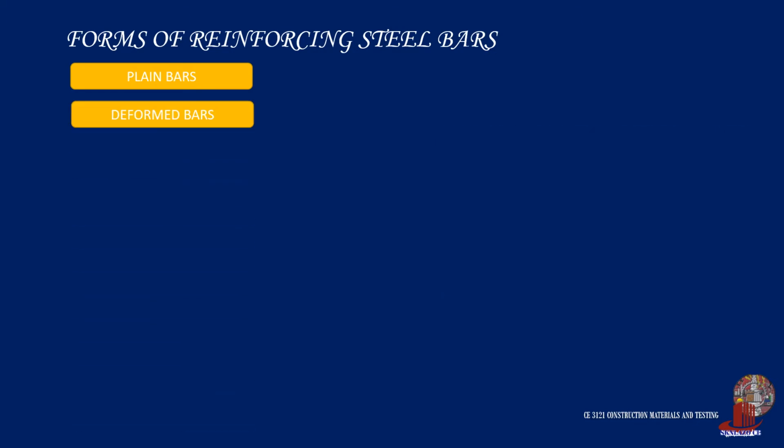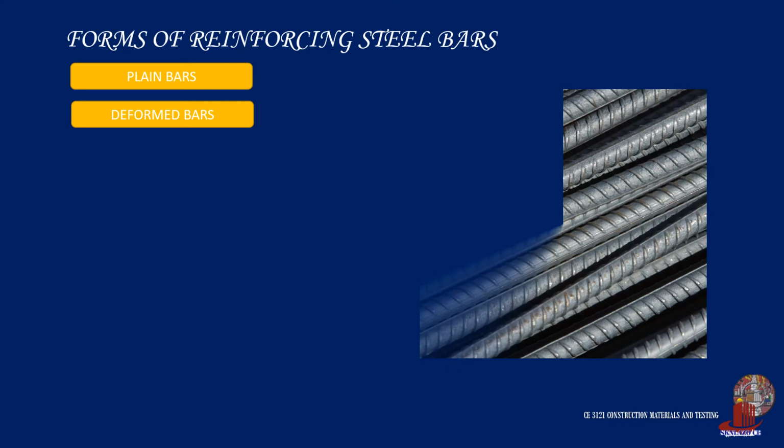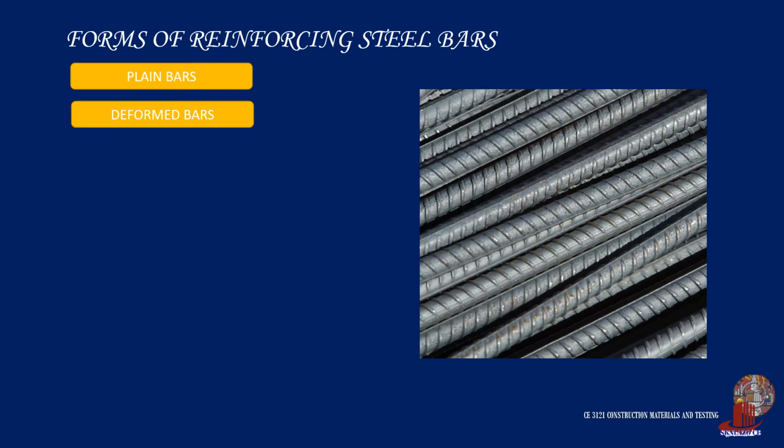Deformed bars contain ridges on each surface, and these marks act as extra reinforcement as they minimize slippages when installed into concrete, thus providing an increase in the bond for the two materials.